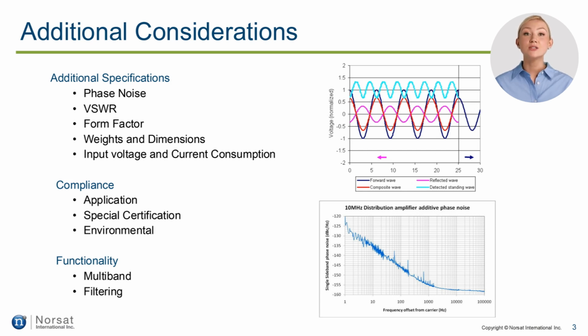The combinations between the tone and the voltages allow the LNB to switch between the internal bands. Make sure that the RF equipment and the setup have this capability if you are planning to use these types of LNBs, or externally control them with a universal LNB controller, or ULC, that can be added in the chain as a separate component.